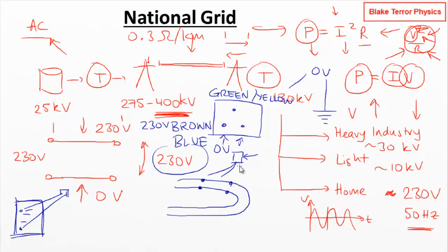This is why we have these big plugs kicking around over here. The fuse that you've got will depend upon the current. You get a different circuit. So although we have these ring mains, you'll get a separate ring in the kitchen, because that's where you've got your high power appliances. So you'll have thicker cables and bigger fuses because you'll have larger currents inside the kitchen appliances. Because of course our voltage is fixed. So if you've got high power appliances for a fixed voltage, then the current has to go up.